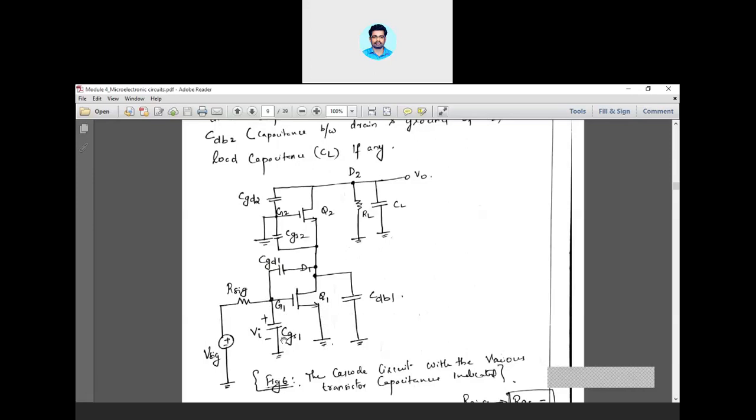Okay, so I can connect this capacitance in between gate and ground. So you have five capacitances now: CL, CGD, CGS, CGD1, CGS1. Apart from these five, another one is CDB1, which will consider the body effect also. You know that in a MOSFET you have four terminals. Even though physically I'm showing three, that is gate, drain and source, apart from that you have a substrate or a body terminal which will normally be connected to source.